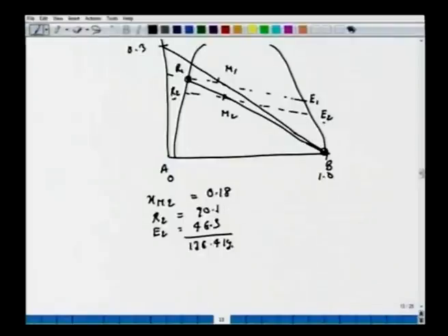All right. So this is the raffinate and E1, E2 here, and these compositions here. If you note down, this composition would be 0.095, and here this raffinate would be 0.227. All right. So again, connect this R2 to the fresh solvent, find the new M3 and find this tie line.